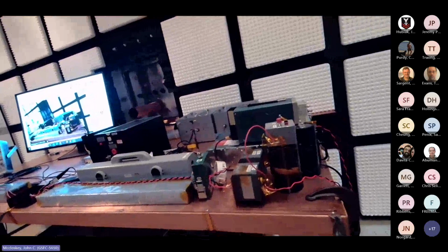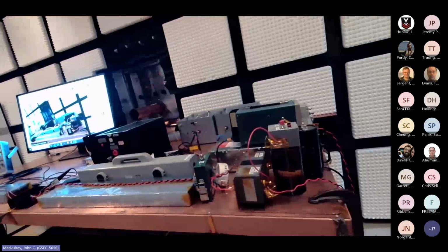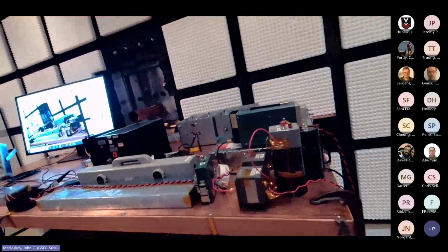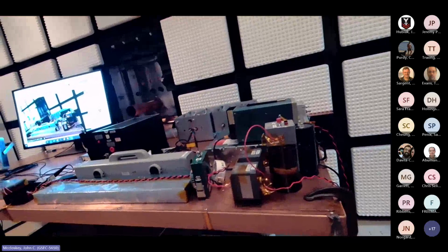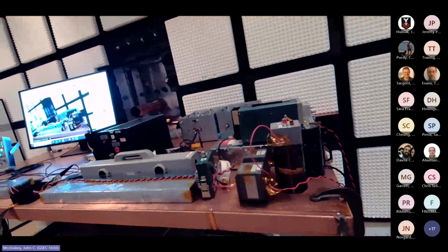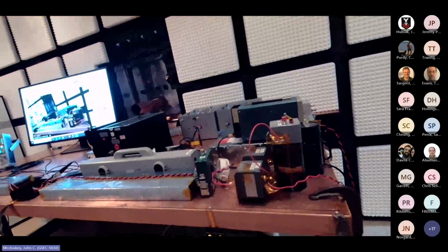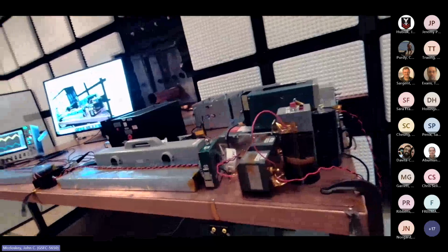But on a spacecraft, we tend to run a dedicated power feed from each load all the way back to the distribution point near the power source. So that common source impedance tends to be much lower. And so for that reason, we at Goddard anyway, we simulate that source impedance. We're intending to simulate a battery.